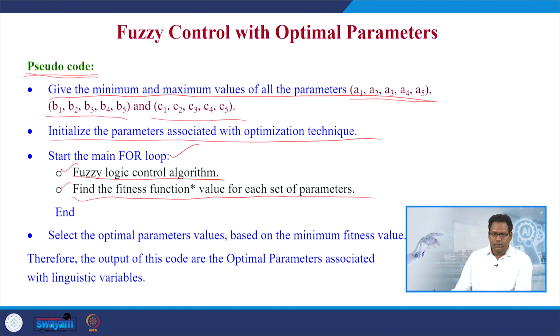whose value has to be optimized or minimized for each set of the parameters. So that it states that with these constraints, with the maximum and minimum values associated with the 15 design variables, we can find the u value, that is control input, and that control input is given to the system model, that is a state space model, and obtain the system response, get the error, and that error is the objective function which has to be minimized at each design variable set.